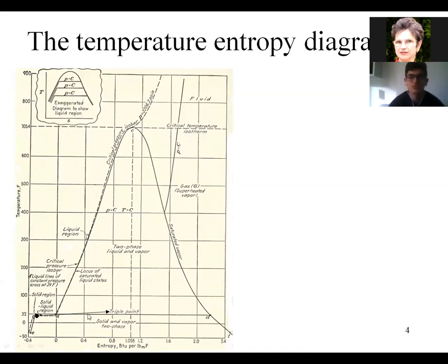The triple point, no, we don't have a triple point here in this diagram. The triple point for water is here somewhere, yes? But at this moment, we are concentrating on this critical curve. So if we want to indicate temperature, the temperature is a horizontal. A vertical means entropy constant. So please take a pencil and make a diagram, temperature, entropy, and draw only this mountain.